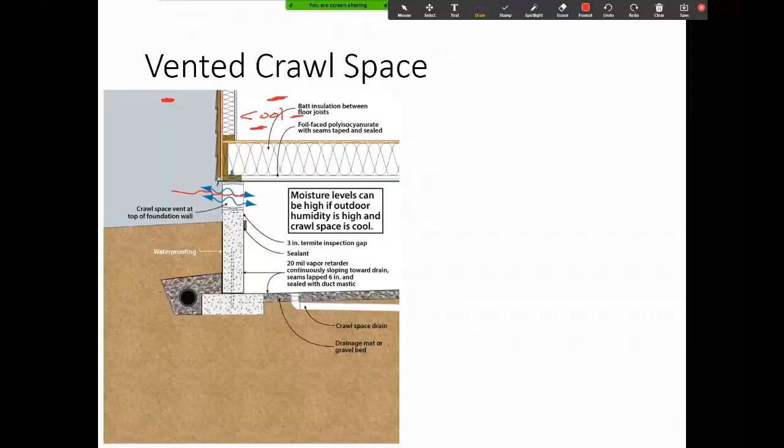But if you don't have a control layer right there and you've just got these floor trusses open to the crawl space, you've got bad insulation up in them. Bad insulation is just fiber; air can pass through that. So when you have warm, humid air going up and getting against your floor, and your air conditioning inside is cool while it's hot and humid out here, that warm, humid air is going to get against the underside of your floor and the water is going to start to condense. You're going to start having water issues. You're going to have mold under there.